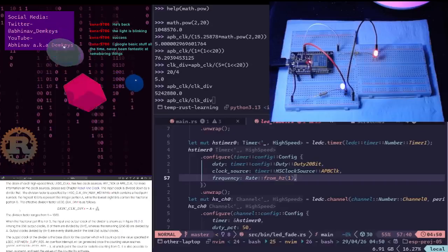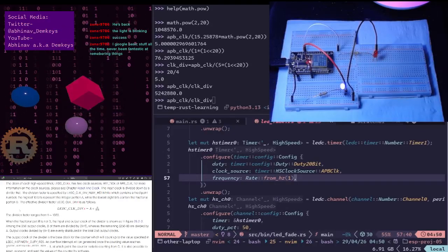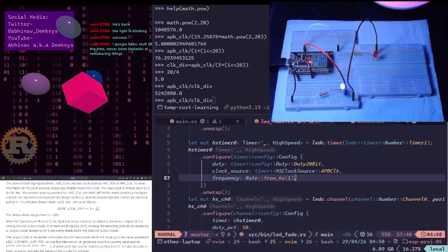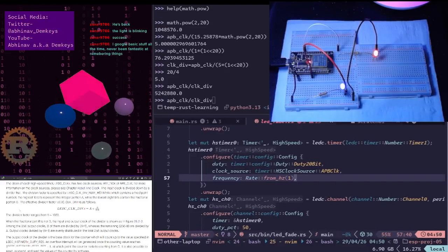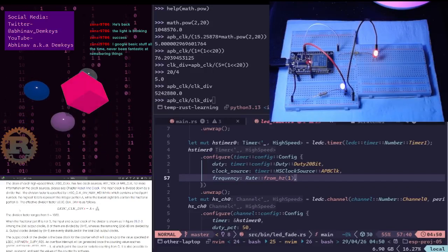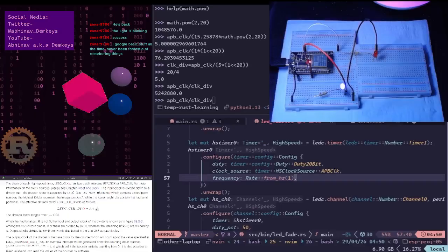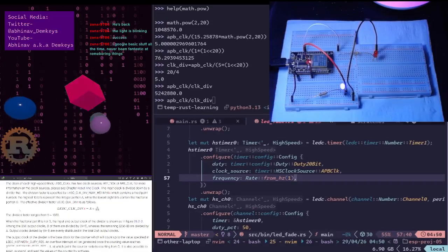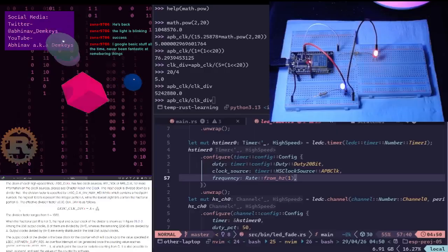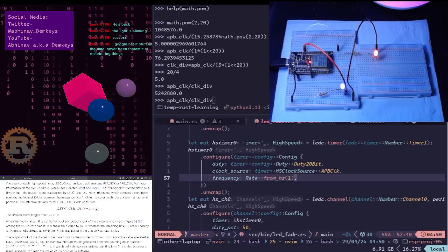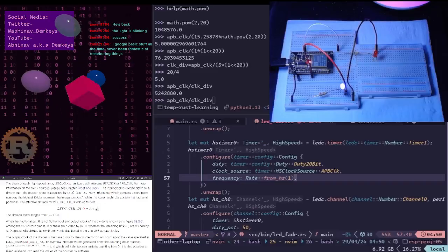Okay, back to what Gemini was saying. Oh yeah, this is where it gets interesting. The hardware, how the division happens. In digital hardware, a clock divider isn't just a gate that stays closed. It's typically implemented using a digital phase accumulator or a counter-based comparator. The integer part, the counter, the most basic part of the divider is a dedicated down counter or comparator.